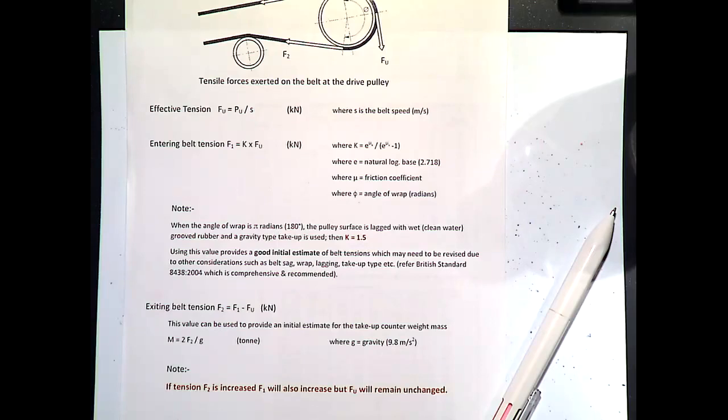So this is one of the reasons you end up having to have this, and you think, hey, it's not like driving around the camber on a road. The camber on a road is trying to help the car from sliding off. Here, you've got to camber it this way to stop the belt coming off this way, but the material makes it a bit easier to shoot through. So there are complications. And there's different kinds of belt and that kind of stuff.